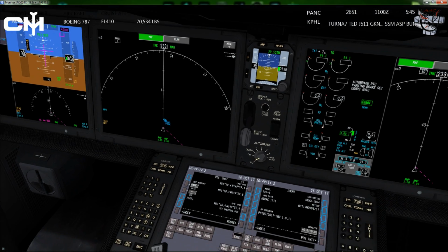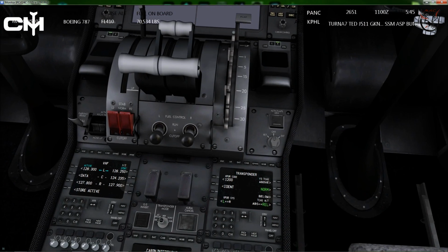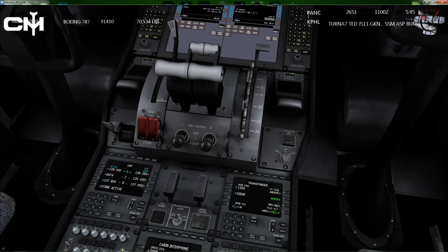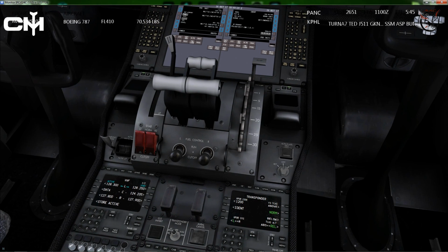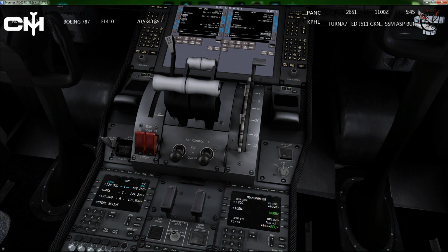And then moving back, and we'll just float on back here. There we go. Speed brake lever should be down. That's this guy. Obviously it is. Reverse thrust levers should be down, and then the throttle should be closed. Flaps should be, it says flaps, where's it at? Oh, it doesn't say flaps yet. Parking brake needs to be set, so there's a parking brake stabilizer. Cutout switches need to have the guard closed. That's those two there. Fuel control switches in the cutoff position. No fire warning lights. We would know if we have lights. Obviously we don't.